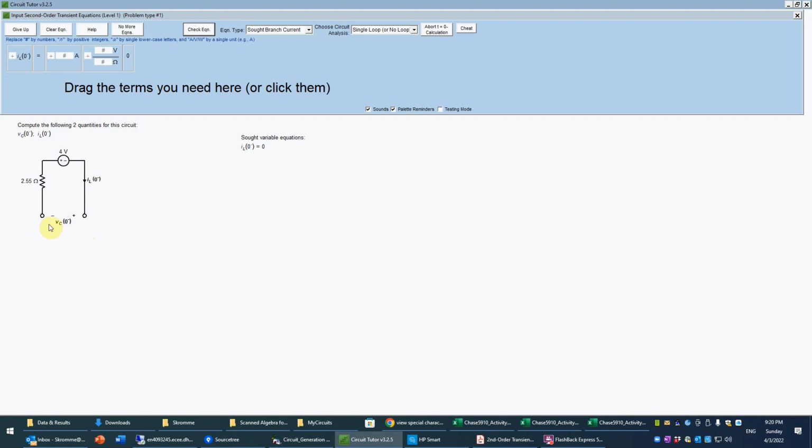And that is correct. And then furthermore, because this resistor is also dangling, we know that it can't have any current. There is no complete path for current to exist in this circuit. And so the current through this resistor must be 0. Therefore, its voltage drop, which is V equals IR, is also 0, meaning that the resistor in effect is virtually the same as a short circuit. Now you're not allowed to change it to a short circuit in the circuit editor, but it can be ignored here.